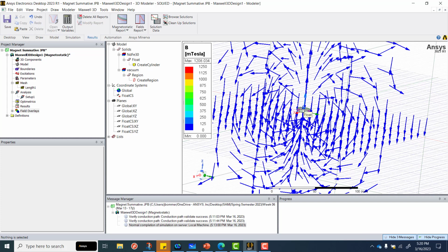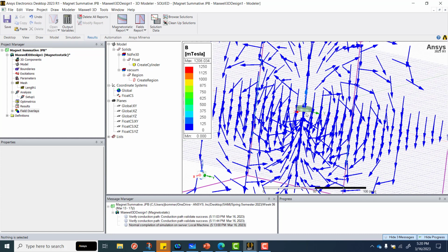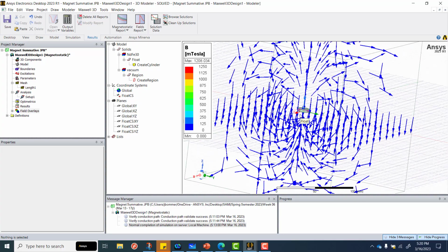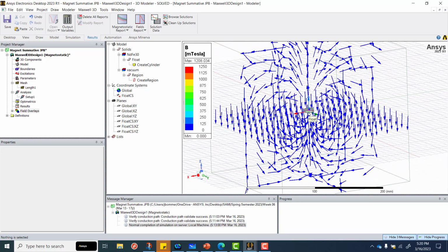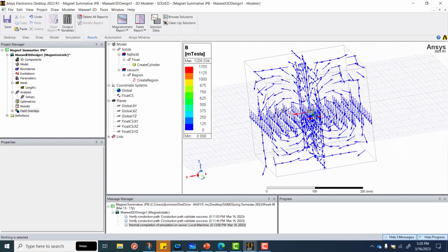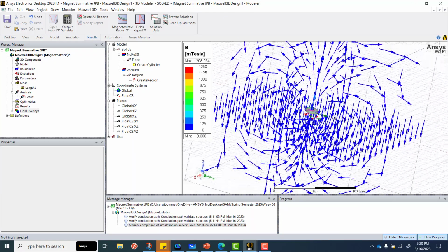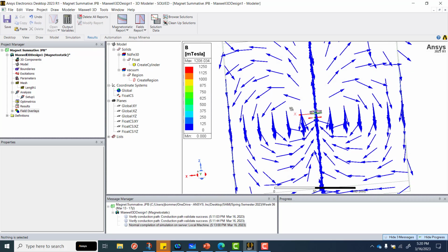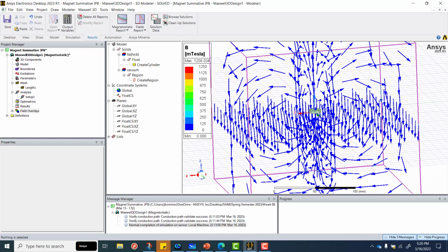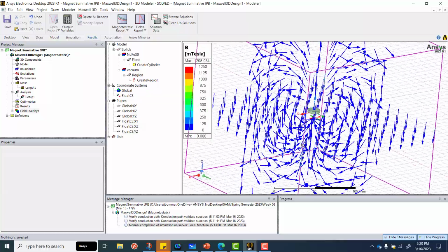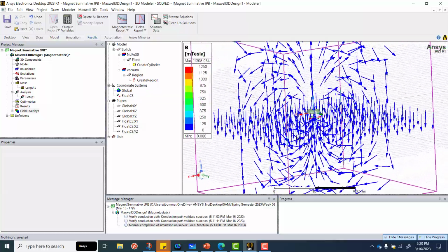and that has a lot to do with the fact that we changed that unit vector in the material setup. By doing this, we're basically telling the material the magnetization direction. For things that take place after that, the magnetic field is behaving in the normal way outside of the region of the magnet. So if you place objects that are magnetic in the vicinity, they should see the effect of these magnetic field forces as you're seeing them here. You'll notice that the fields, the vectors that are plotted in the x-plane, are all pointed down in that direction.